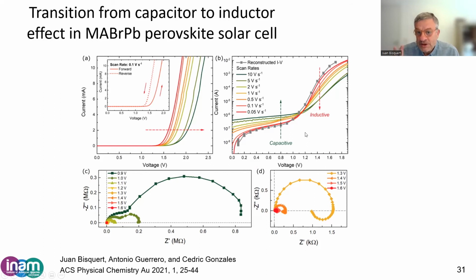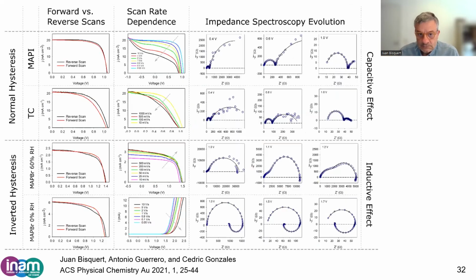So now we can quantify the hysteresis not just by measuring it, but we can first make an impedance measurement, and the structure of the equivalent circuit will tell us what is going to happen with the hysteresis. And we have presented many different analyses, and they are basically coherent: the direction of hysteresis with the dominant elements of the equivalent circuit at low frequency.